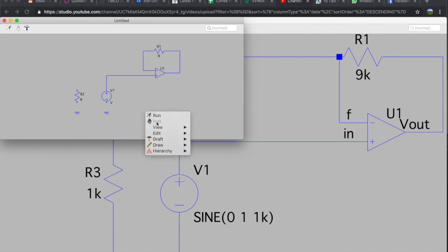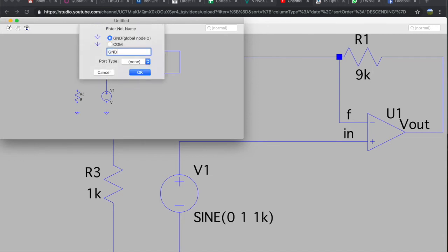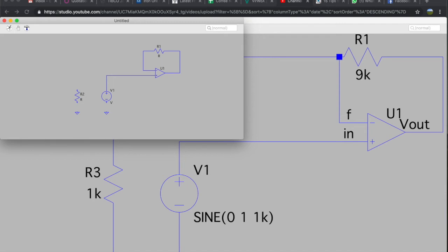If you want to duplicate a component or change its value, you right click on it, and it'll give you a menu as well. That's actually how you change the values and labels of components. So you right click, and in this case it'll bring you the label for ground that you can type in. If you right click on something like a power source, it'll let you change the voltage on the power source as well as the name. So it's very basic, and it's quite intuitive. It's a little bit complicated on Mac, I think, because it doesn't have toolbars. But I've heard, or I think I've seen, that on Windows it does, so that should be a lot easier for the Windows users.